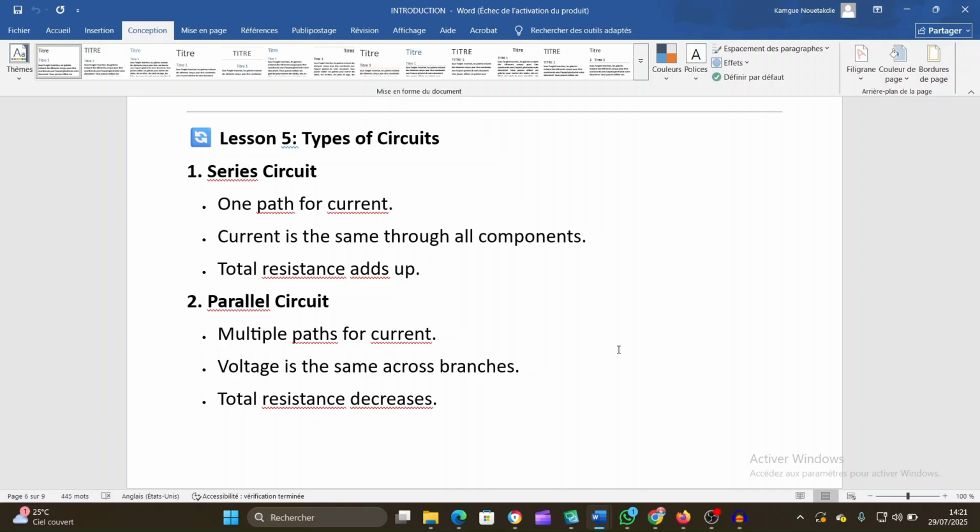We need to use insulated tools when we are working: an insulated screwdriver, insulated pliers, and then equally we can wear insulated gloves. We also said we need to turn off the power before we work. Yes, turn off the power before we work. We go to the breaker, we put it down, we switch it off, and we wear rubber gloves when needed.